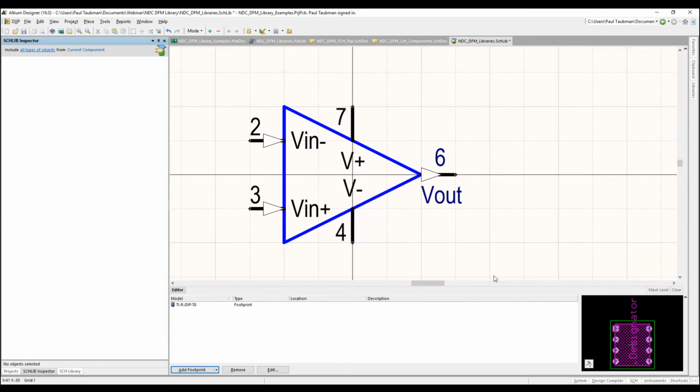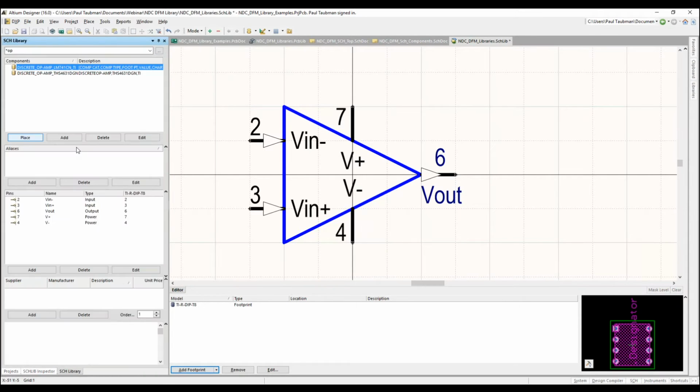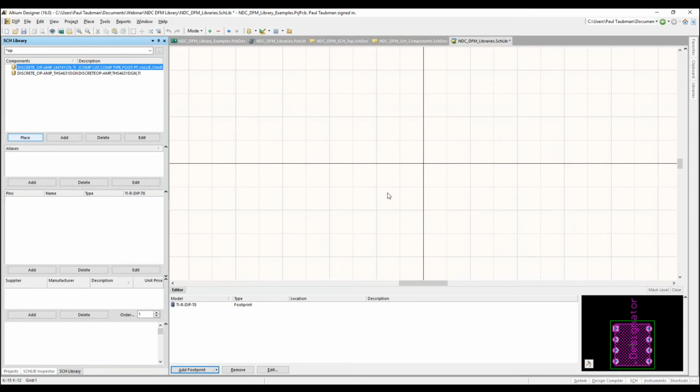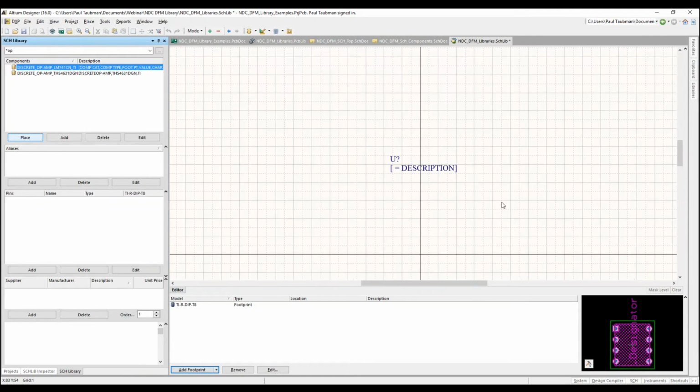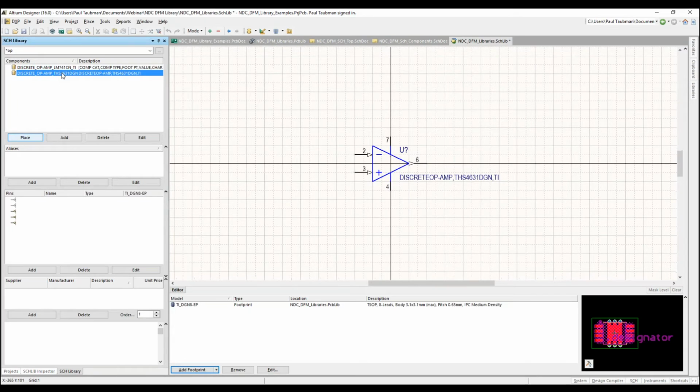What I'm going to do now is talk about alternate views. And this is a point of confusion for a lot of people. If you're new to this, you can get pretty spooked out by it because of the way Altium presents it over here. There are some buttons over here that, if you don't know what you're hitting or what they're for, you can get pretty freaked out. So if you hit this plus button over here, boom, it just blew away my design. So what happened to it? Then everybody's in a panic. It's like, well, wait a minute, I see this. Did it just wipe out my design? What's going on over here?